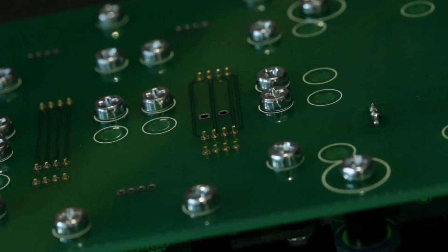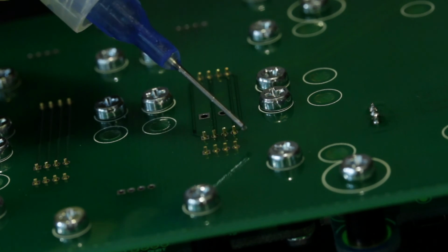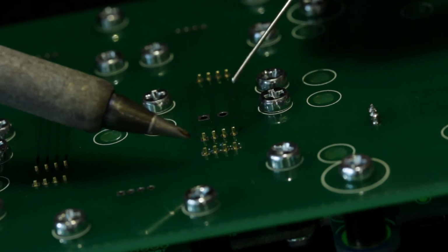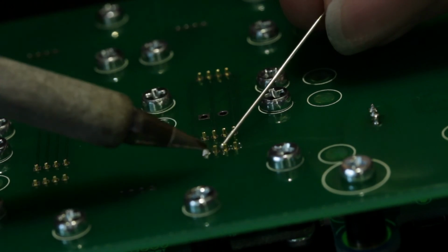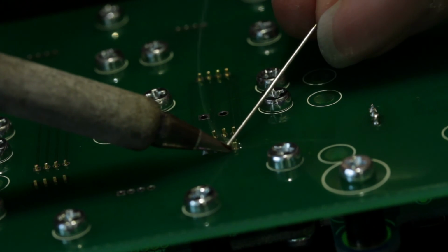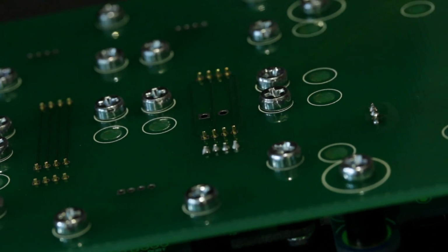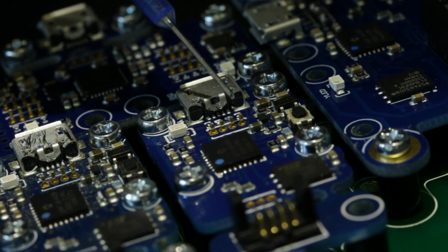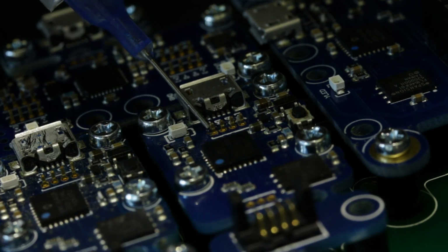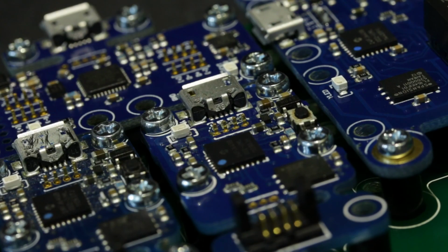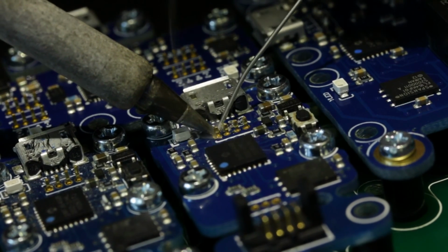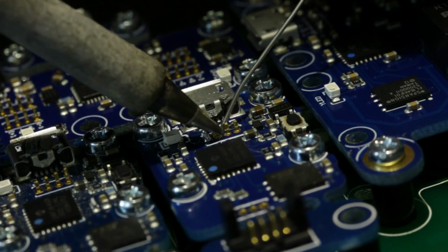Once you have put all your devices, now you can start the soldering. So always start by putting flux. Flux helps tin to wet the contacts well and to avoid creating bridges. You put the soldering iron on one side of the contact and you come on the other side with the thin wire to produce nice solder points. Same process on the other side where components are located. So there you have to make sure you don't touch other components with the soldering iron. Start by putting flux as before and then come with the soldering iron and the thin wire on the other side.